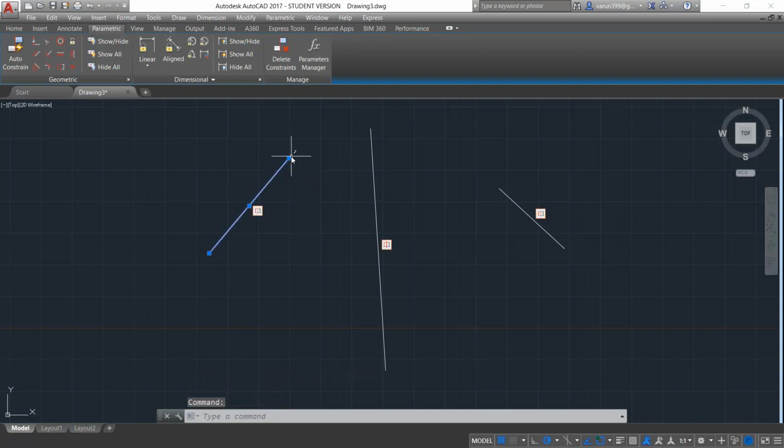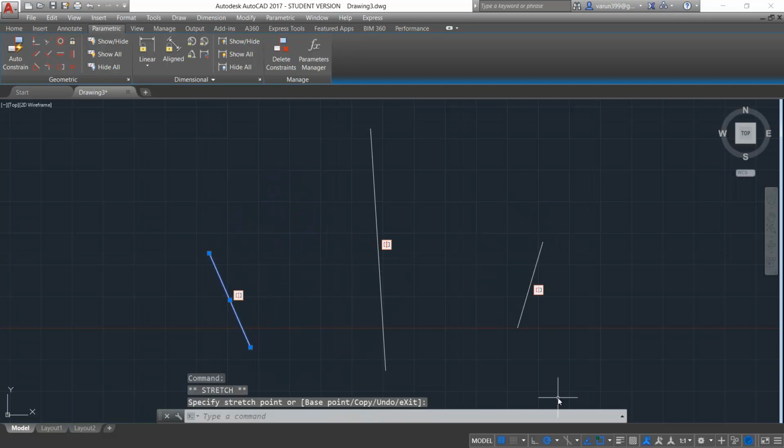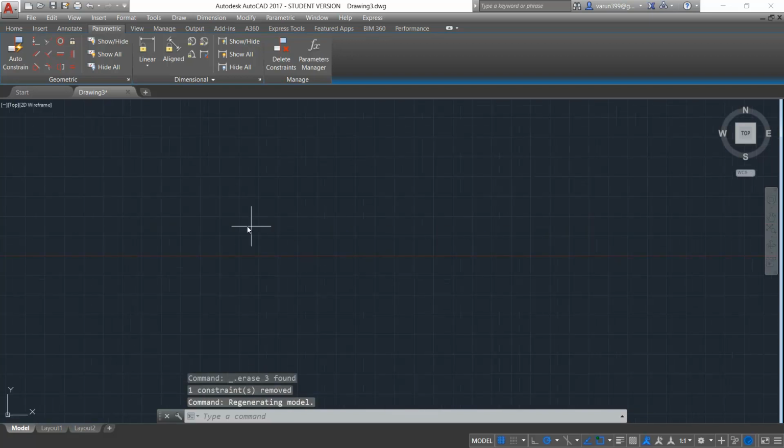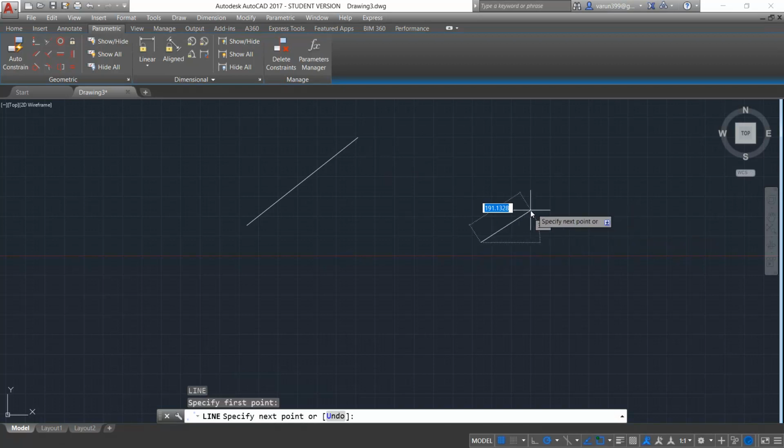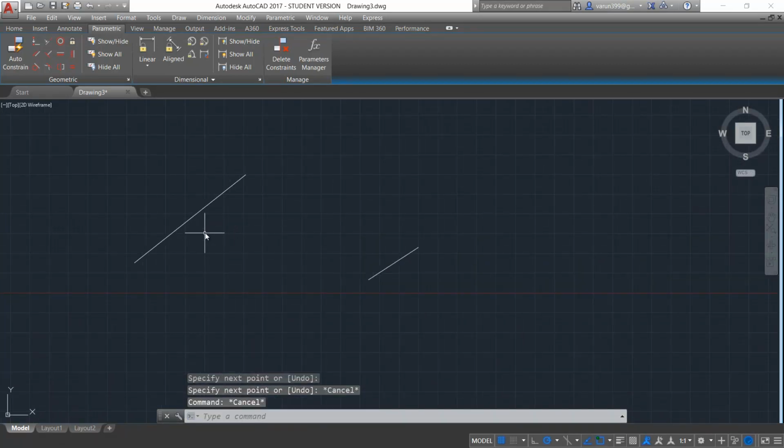So this denotes that when you rotate or move this line, it will automatically affect the other line like that. So it's pretty easy if you design the object in a symmetric way. Now, you can make use of the last constraint very easily, and it is very useful when you're designing many complex structures. Suppose I want this line to be of the same length as this line.